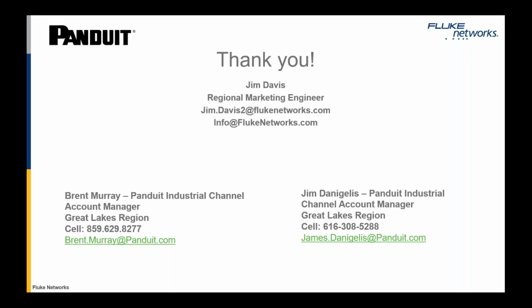But when you start to consider multiple sources of noise, in a commercial setting we're most concerned about power and data being next to one another, but in the industrial environment we're concerned about that, and we're also concerned about RF noise and high frequency noise also occurring, right? So the industrial cable may have additional layers of shielding on it, which you've seen, and we covered some of that, that braided version of shield added to that cable design.